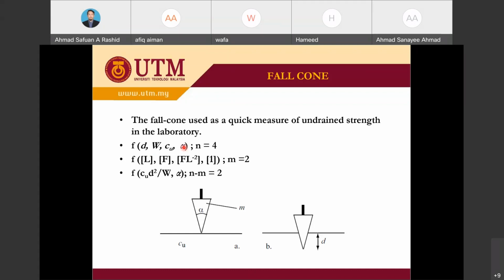So that is for the four cone method. Actually, I'm using this equation for my master project study, where we want to determine the plastic limit value by using the four cone method rather than the thread rolling method or the Casagrande method. This formula has been properly developed by Wood and Rowe from Oxford University.